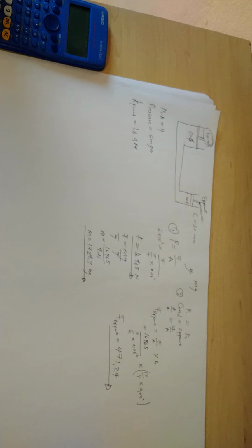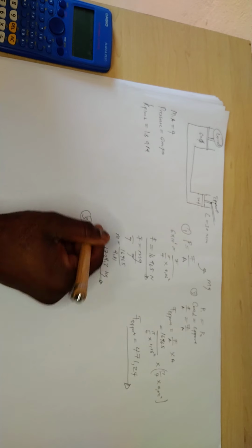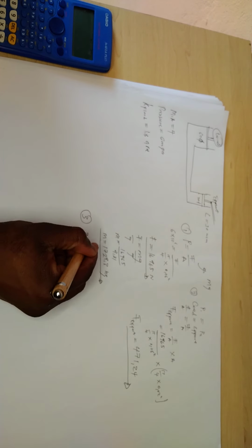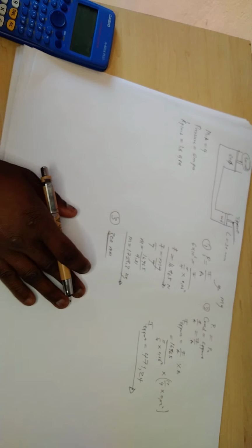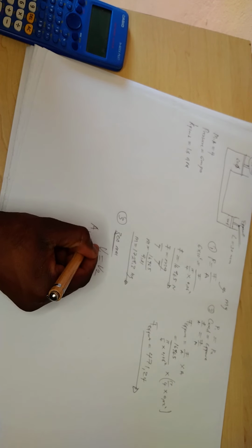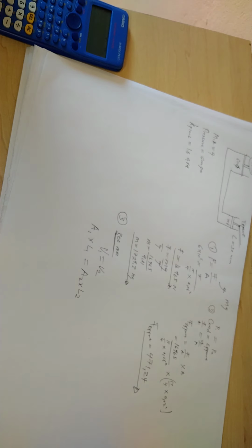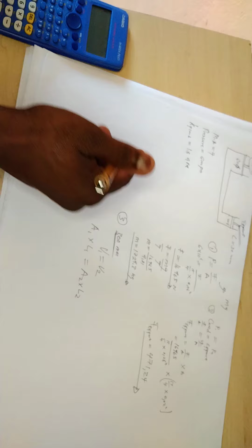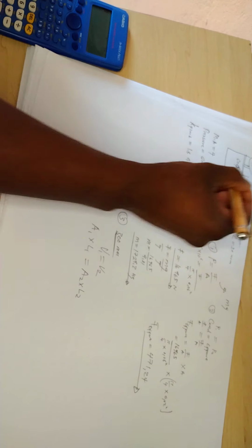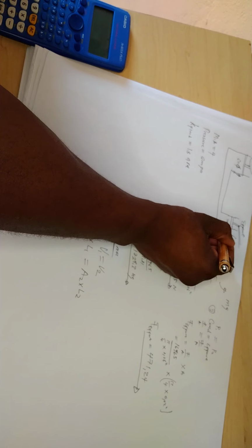So here they say the number of strokes that the planer must make to lift the mass of 300. So it means we need the length. Remember I told you that they gave us on number 3, they gave us the length, which is 300 millimeter. So this is the length, right? And I told you that volume 1 is equal to volume 2. Then area 1 multiplied by length 1 equals to area 2 multiplied by length 2. So what we want here, we want the length of a ram, because they gave us 300 as the length of a planer over here, right?